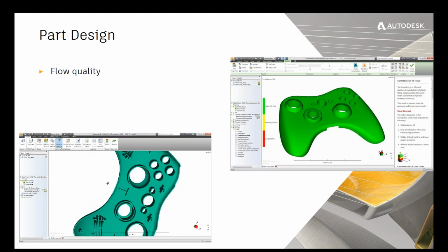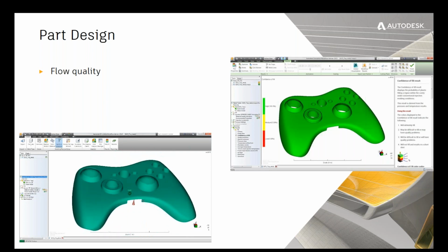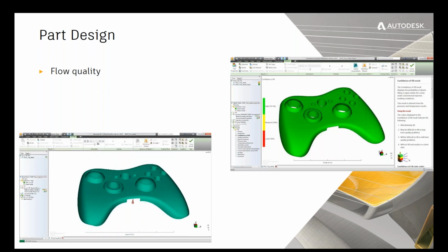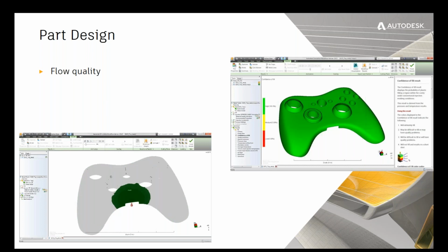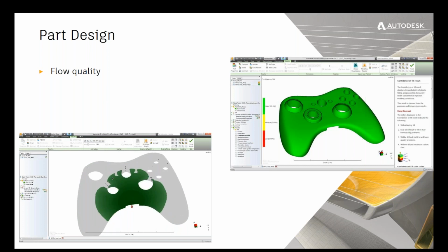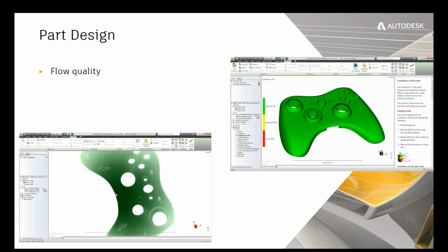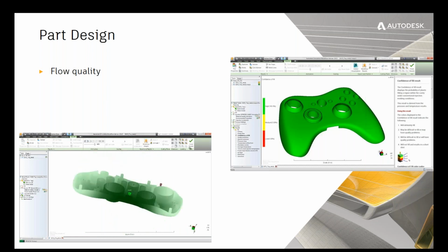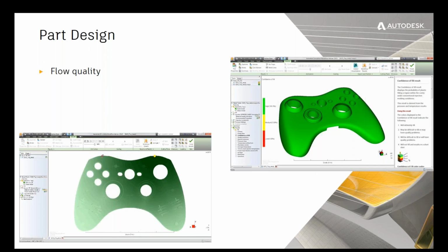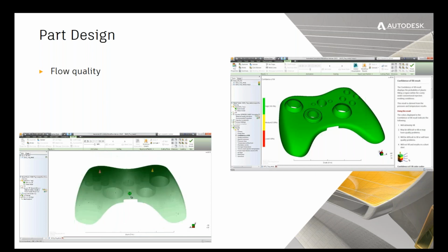You're able to preview the fill by placing an injection cone on the CAD and verify how materials will fill the part and where weld lines and air traps will occur. You need to ask yourself if the location is acceptable or if the surface is a Class A surface. Are weld lines going to cause aesthetic or structural issues based on the product functionality?